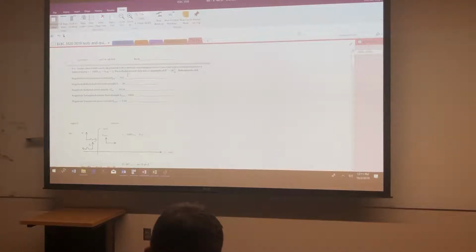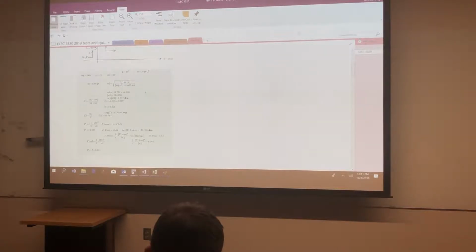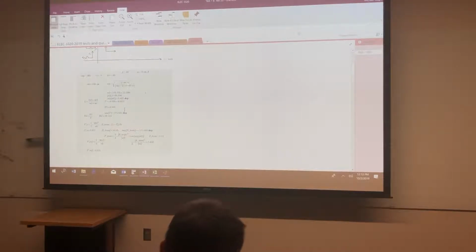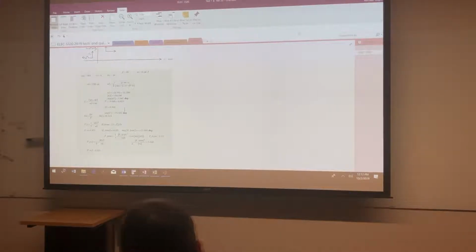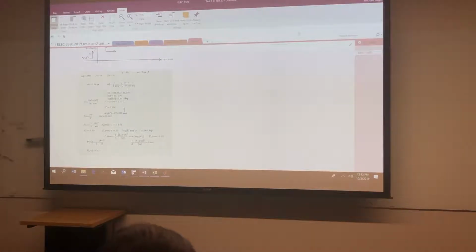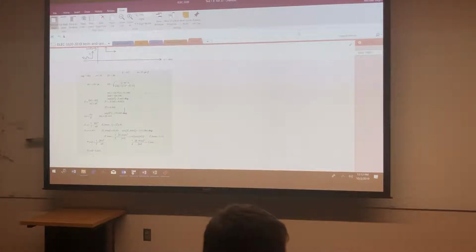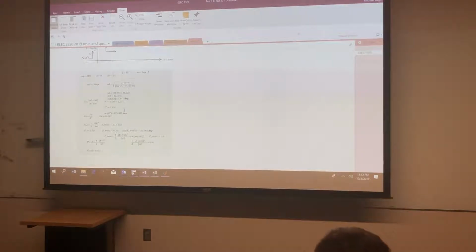This one's straightforward, same thing again. First you have to get A to 2. After you have A to 2, then you have to get the reflection coefficient. After you have the reflection coefficient, you divide the reflected field by the reflection coefficient to get the incident field. After you have the incident field, you get the actual power, you can go ahead and get the transmitted field as 1 plus the reflection coefficient, right? That's tau, times the actual incident field is the transmitted field.